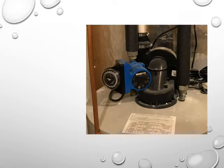And here we have a close-up of the pump itself. This is connected to the hot water side of the water heater. It also has a very nice timer. This is a 24-hour timer. And generally, if you wish, you can set it up as often as 15 minutes on and 15 minutes off. Typically, we're not going to see that. I personally have it set up for 15 minutes, running 15 minutes out of every hour. And then you set it to start in the morning whenever folks get up, and you turn it off in the evening whenever you're done using the hot water. Typically, when you're hitting the sack.